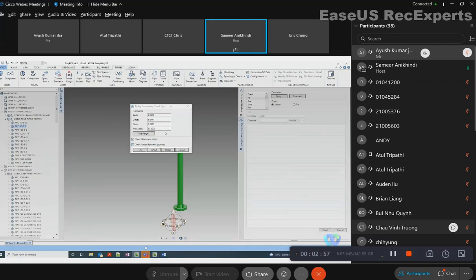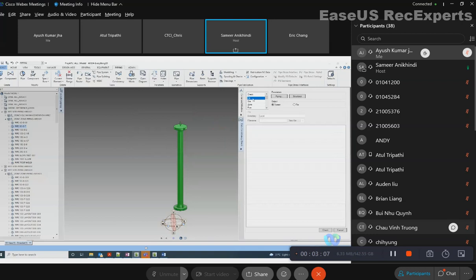But these are all options. You can set it back to default, whatever the product setting is. And click OK, and then to check it, you either select complete site and check all the pipes in it, select zone, select pipe, select branch, and for structure option there are structures, or you can have a particular name. It asks you for a name, right?